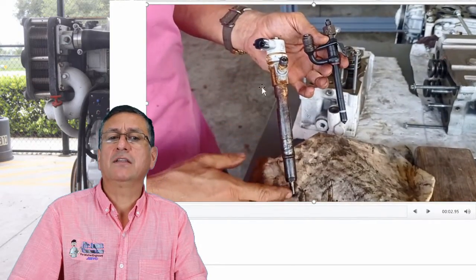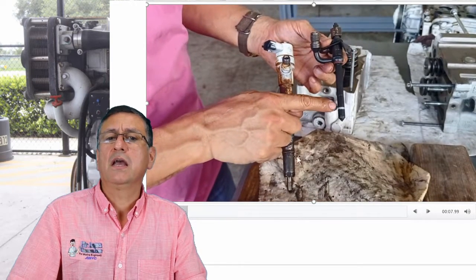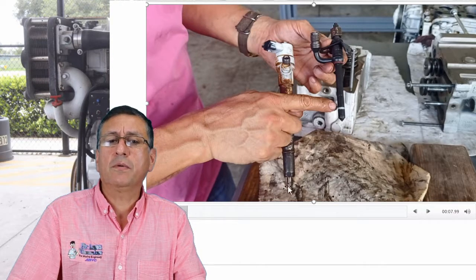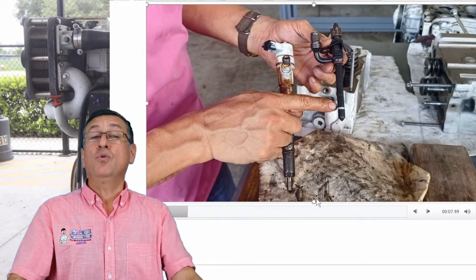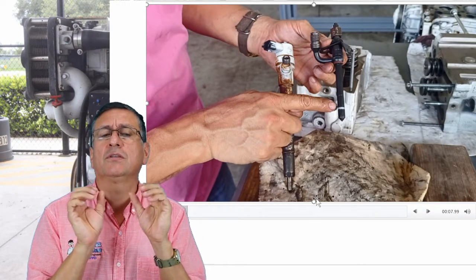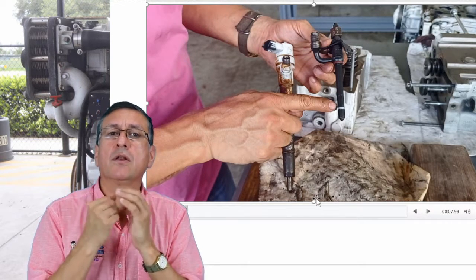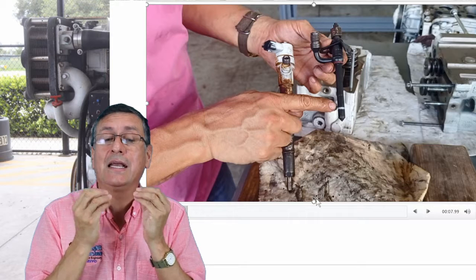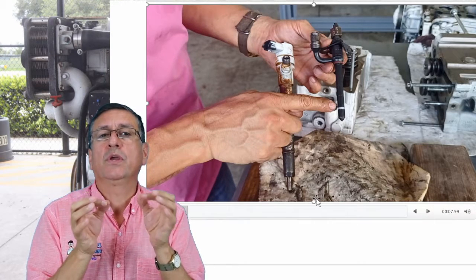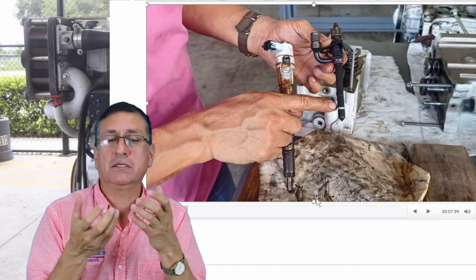Okay, this is the mechanical and this is the electronic. Alright, be careful with those O-rings. One O-ring in the bottom, other on top. Here we have one washer in the bottom and another O-ring on top. In some cases those washers are plastic, in some cases they are copper, and in some cases it's not a washer, it's a rubber O-ring. Those O-rings are critical, my friends. Always when you remove the injector, you need to verify the condition of those washers or O-rings and replace them.